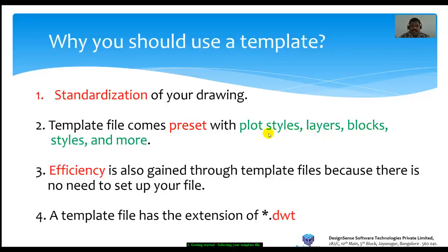Templates have the standards of your drawing. All your drafting standards are in the templates. So what are the standards? A template comes with a preset of plot styles, layers, blocks, text styles, dimension styles, and more. Efficiency is also gained through a template file because there is no need to set up your file. Always remember, a template file has the extension .dwt.